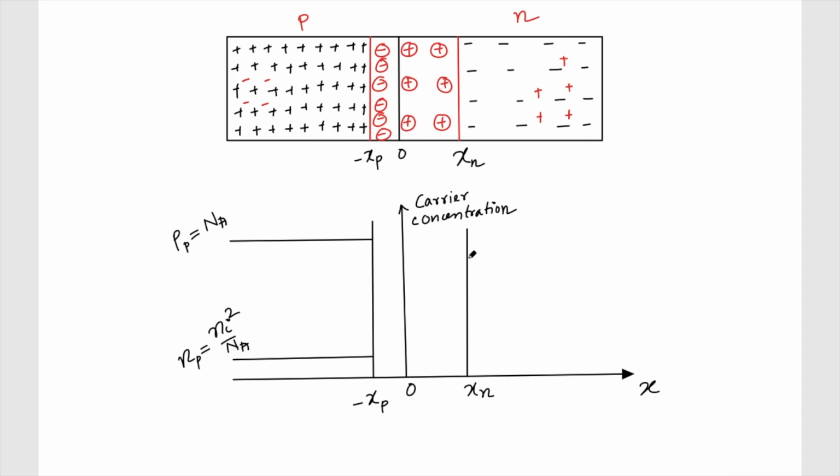So basically these are the electrons, the minority charge carriers, and we have some minority charge carrier in the N side. So again, since the doping concentration of this side is smaller, the electrons, the majority charge carrier on the N side is equal to Nd, and this Nd is smaller than Na, and observe that the minority charge carrier will be more in this N side because we know that the minority charge carrier, the holes on the N side, will be equal to Ni square by Nd.